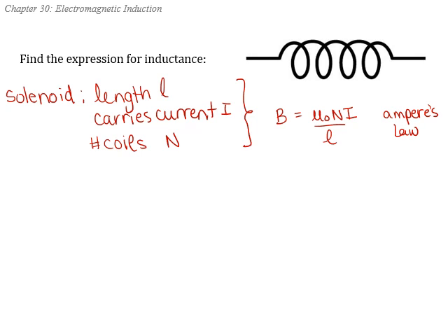So in our inductor shown in the picture, I'm going to say that the current comes up from in back and around down in front. I know it's hard to draw 3D. That leads us to a magnetic field, if we use our right-hand rule, that's going to point towards the right, and it will only exist inside of our inductor if we're assuming that it's ideal.